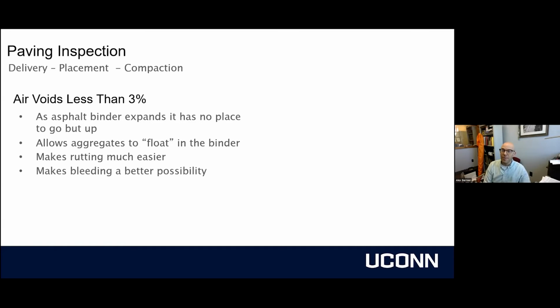driving condition. With Superpave dense graded mixes, it's very unlikely that we're going to overcompact them just because of the nature of their gradations. So avoiding rolling a mix because you're concerned about this usually is a little too conservative of an approach. In most cases, you can beat the tar out of it.